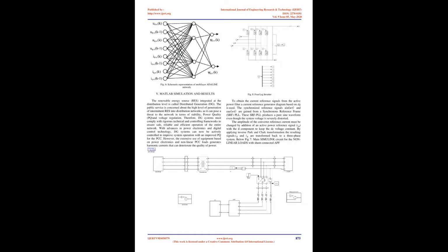The three-phase supply voltages, Ua, Ub, Uc, and currents, Ia, Ib, Ic, are transformed using the Clarke transformation, or αβ0, into a different coordinate system which produces instantaneous active and reactive power components. This transformation can be seen as a projection of the three-phase quantities onto a stationary two-axis reference system. The Clarke transformation for the voltage variables is given by.